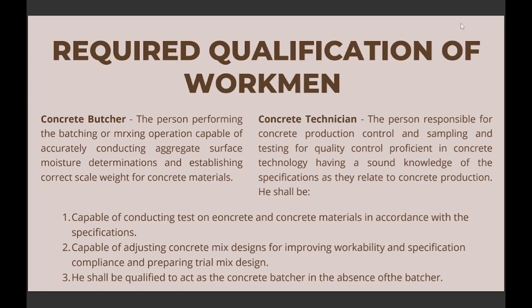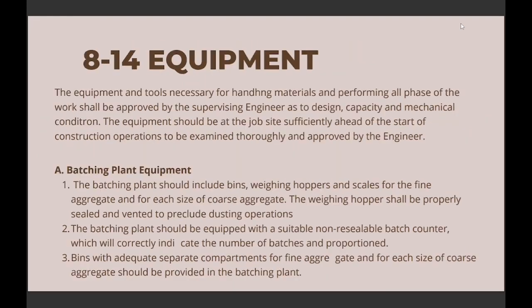Concrete technicians. The person responsible for concrete production control, sampling, and testing for quality control, proficient in concrete technology, having a sound knowledge of the specifications as they relate to concrete production. He shall be capable of conducting the tests of concrete and materials in accordance with the specifications. He should be capable of adjusting mix design for improving workability and specification compliance and preparing trial mix designs. He shall be qualified to act as the concrete batcher in the absence of the batcher.